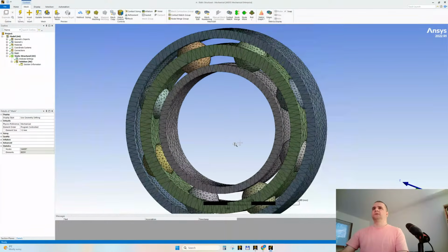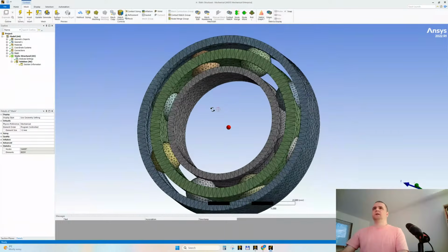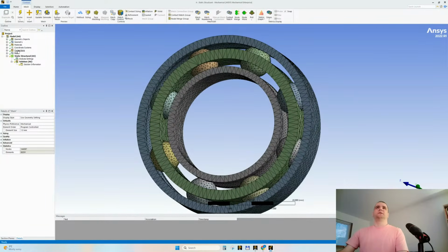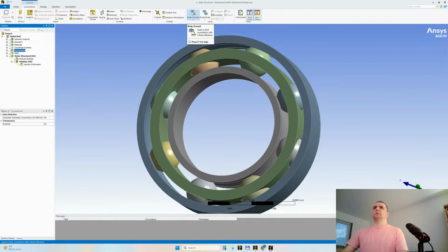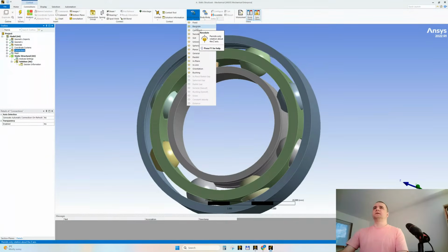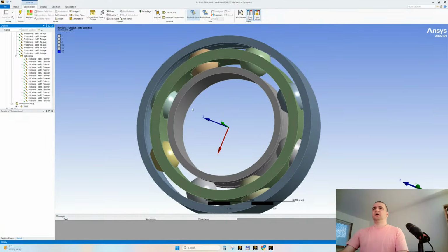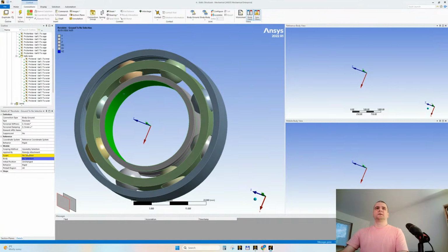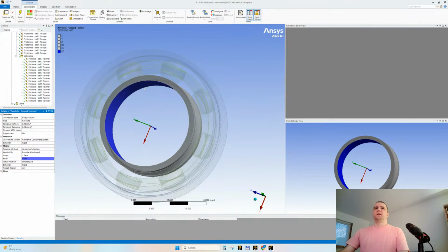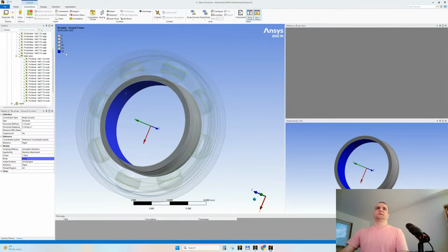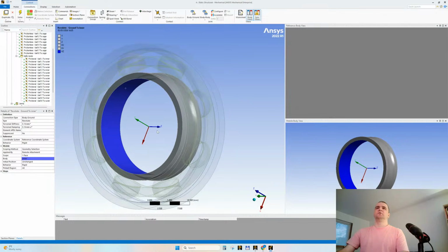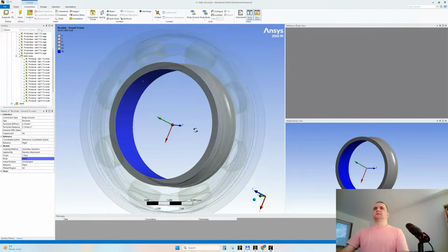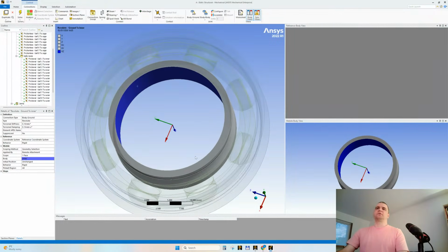How do we do this? There are multiple ways. The one that I like very much is this one. Let's go for body ground and select a revolute joint. I will click this face, scope, apply. The rotational axis is Z. We'll have rotation, RZ, rotation about the Z axis. You'll see in a few seconds the corresponding circular arrow.